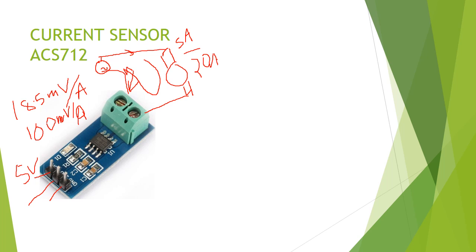Okay, so we need to put some resistance so that we can have a difference between these two. This is called a pull-up resistor, and we will be using it. The pull-up resistor generally distinguishes between the voltage level of this VCC and this data pin.